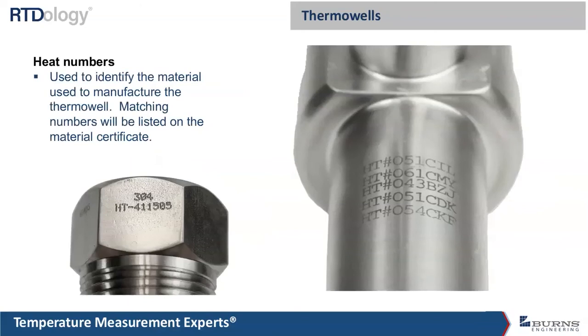Heat numbers you will find on the Thermowell, and these are important for identifying the chemistry of the material that was used for the part. Now these will typically have a prefix of HT on them most of the time. Sometimes it's just going to be a bunch of numbers and letters, and they can be confused for a serial number.